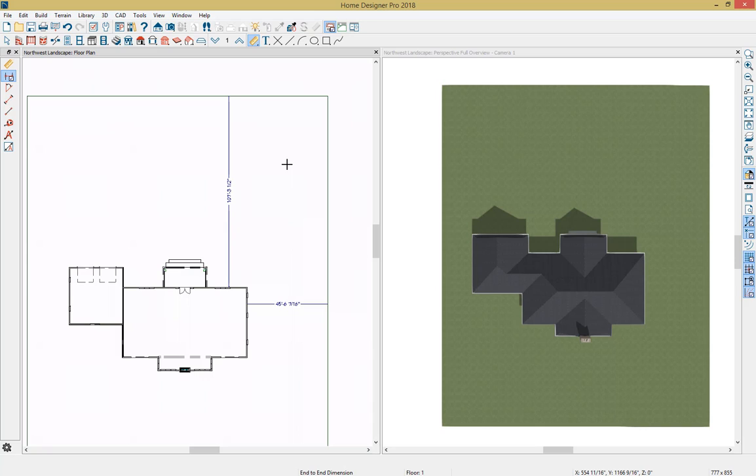So one tool that I'll be using frequently throughout this demonstration is the space bar on my keyboard, and that will allow me to drop whatever tool I have selected and then freely select objects again. You can also use this tool right here called Select Objects, and it will do the same thing. But now I'd like to use these manual dimension lines to relocate my terrain.